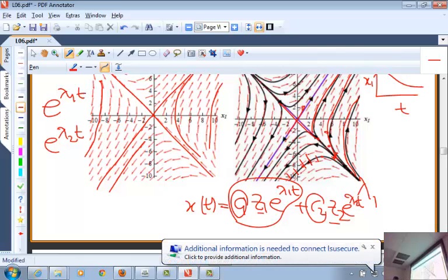When we were working on hydrodynamic stability problems, about 10 years ago, there was a lot of discussion about this. The question is, if there is an unstable state in a fluid mechanics problem, can you reach that state by using time integration of a dynamical system? The answer turns out to be no, because in physical systems you can never observe that unstable state because there are always random perturbations in the pumps, vibrations, or whatever. In computers, the random perturbations come from round-off errors. So you will never be able to get to those unsteady states.